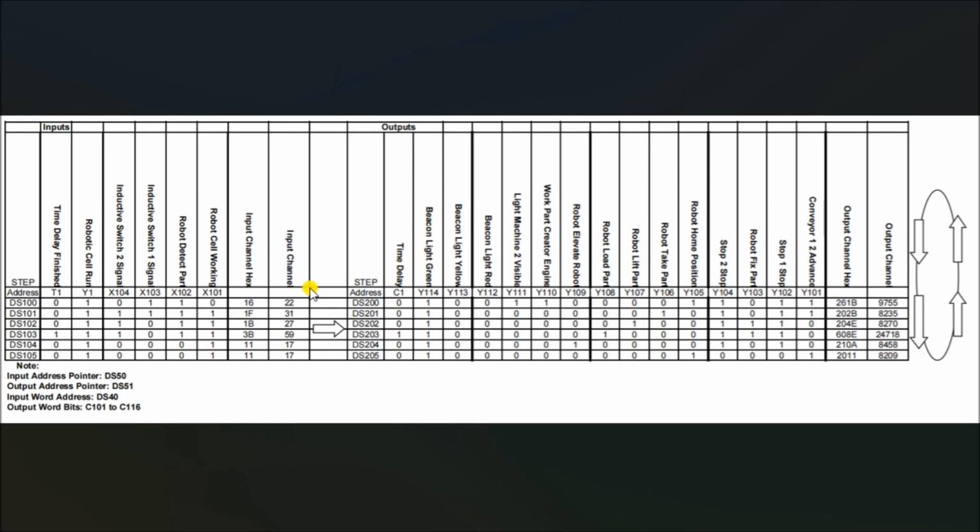So the first thing we do is we put those outputs on, and then look for that next input. If these input signals are on, then the next output sequence comes on. Now, we've also addressed this in our DS, which is part of our Click PLC program, and where these addresses are coming from. So that is fully part of your developing of the logical sequence of operation.